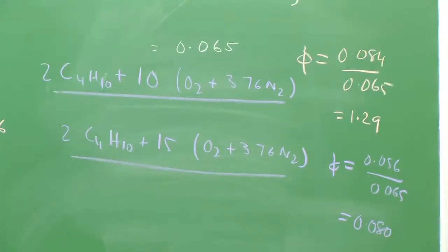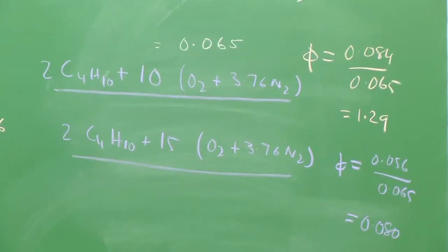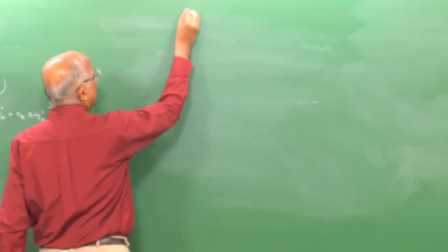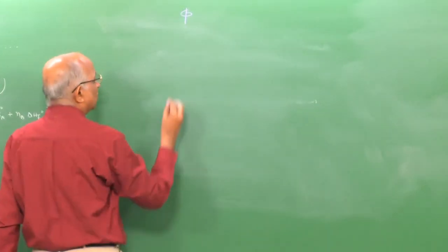Therefore, what is it we have done? Let us quickly summarize this before we go to the next part of our problem, that is to evaluate the heat content. Whenever you have fuel vapor mixing with air, it need not always be in the stoichiometric proportion, that is, forming completely oxidized products of combustion. We said, well, you had an equivalence ratio.